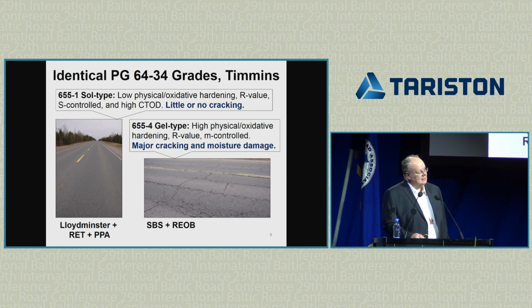On the right, at 8 years of age, we had a section which has SBS polymer and some motor oil added to it. They don't mix very well with asphalt cement, so it phase separates, you get moisture damage, you get low temperature cracking, you get block cracking, you get fatigue cracking, you get potholes, you get everything for free.